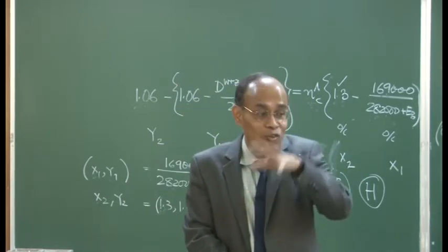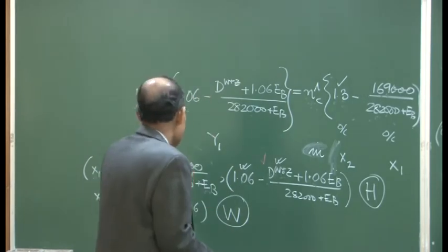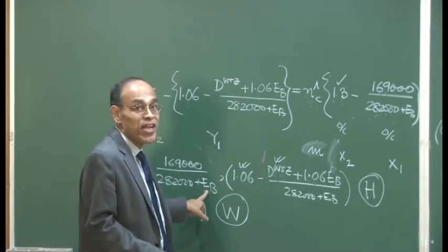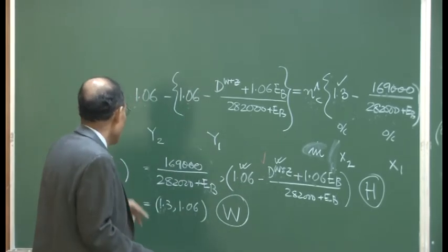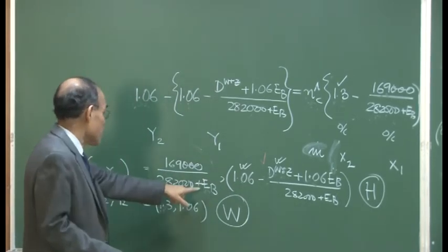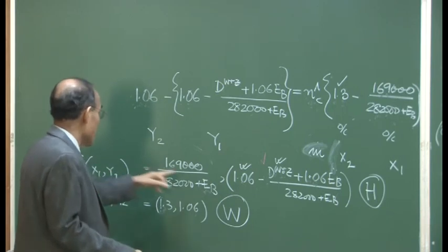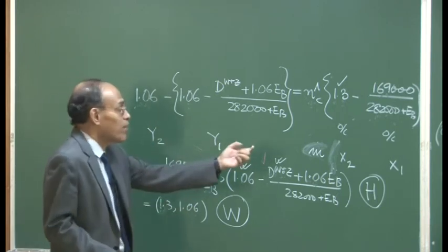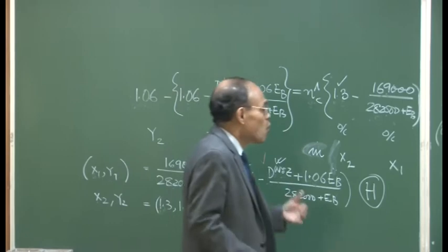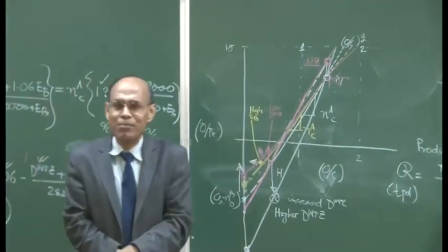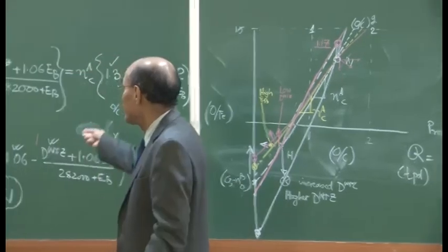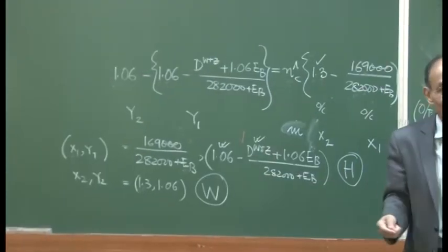Okay? That is going to be the ratio of nitrogen to oxygen, as a result of which the enthalpy of the blast is going to be changed, it becomes more with oxygen enrichment, and then this point will try to move in the left direction. So, oxygen enrichment increases the blast furnace productivity, that we have made as a qualitative statement, but in terms of the equations that we have established, we can also visualize it.